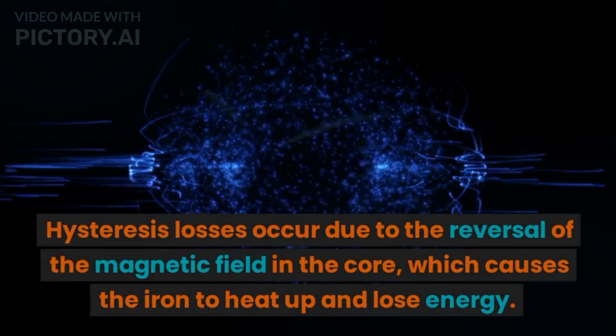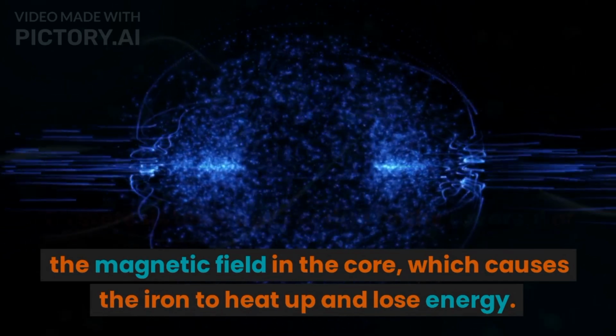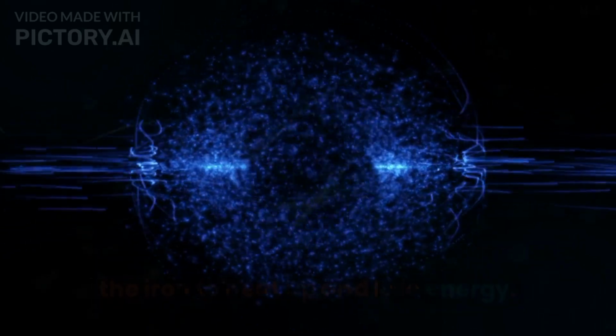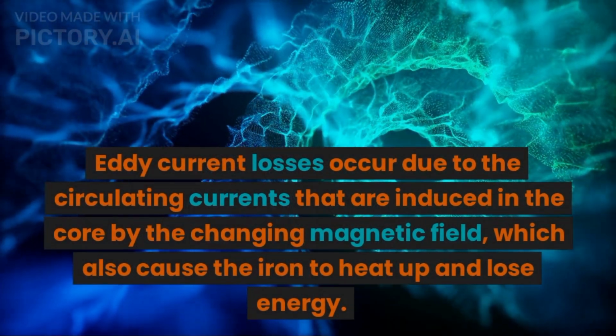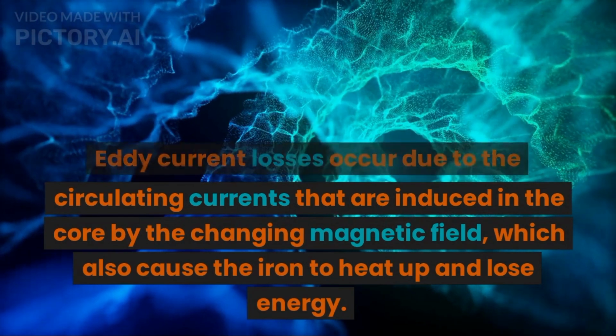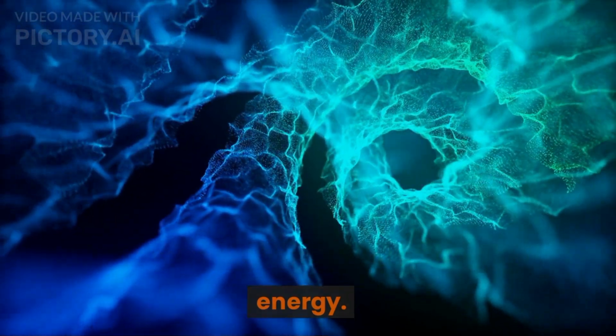Hysteresis losses occur due to the reversal of the magnetic field in the core, which causes the iron to heat up and lose energy. Eddy current losses occur due to the circulating currents that are induced in the core by the changing magnetic field, which also cause the iron to heat up and lose energy.